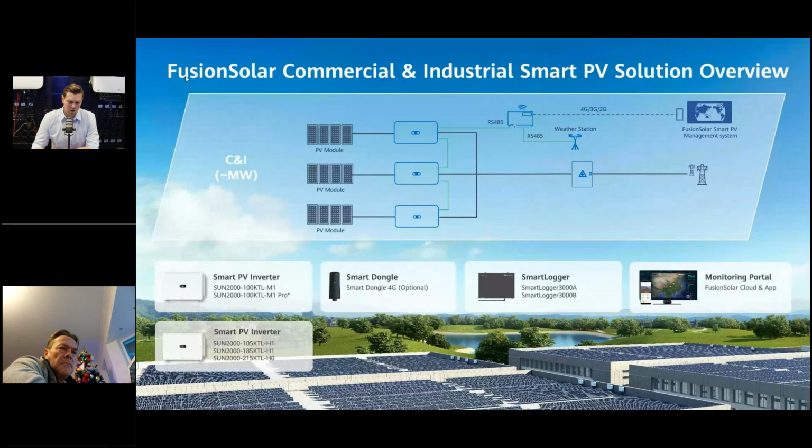The smart logger is the product which is actually used with the industrial scale inverters. So this is the brain of our system. It collects all the data. It sends the commands to the inverter, registers all the parameters and monitors them. It also allows us to connect it with a third-party monitoring platform or some externally controlling system, for example for the grid operators to control our PV plants. So this is like the heart and the brain of our whole system.